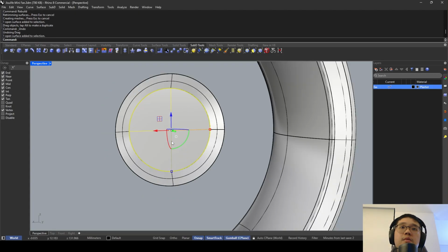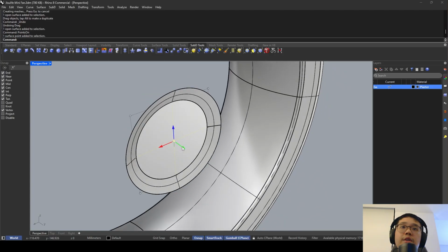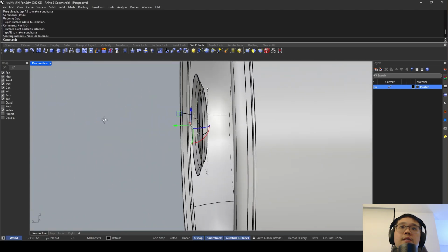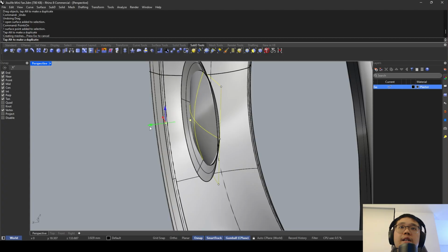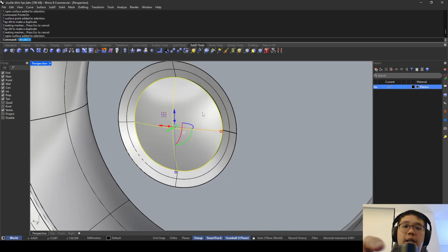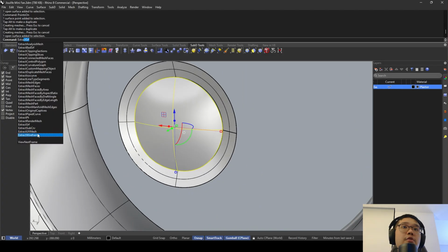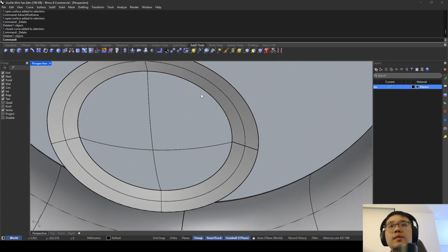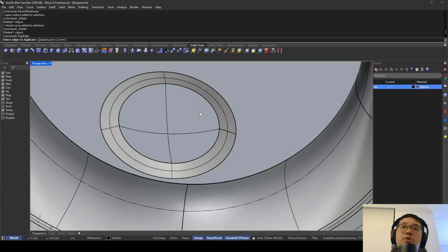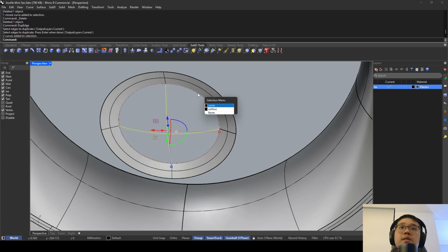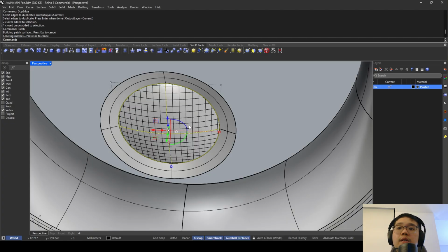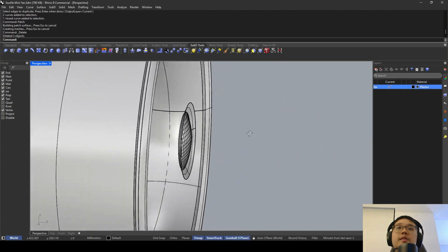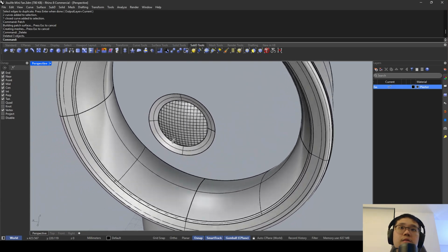Points on. Click the point in the middle, bring it outwards. Something like that. Extract wireframe, delete off the surface, delete that, dupe H again, select all this surface, I mean curve, patch. Looking good.